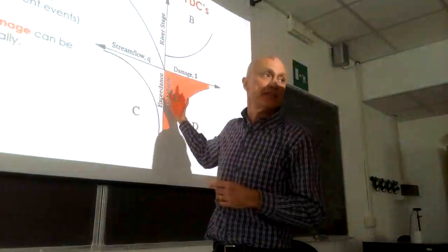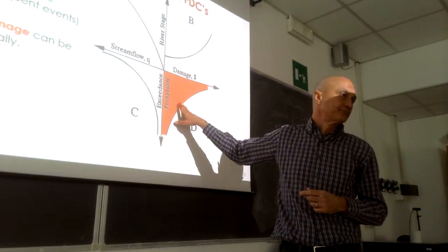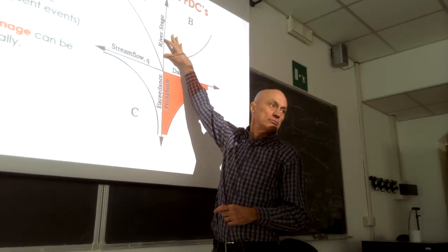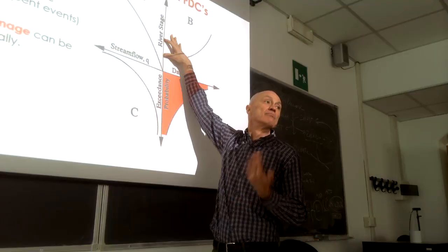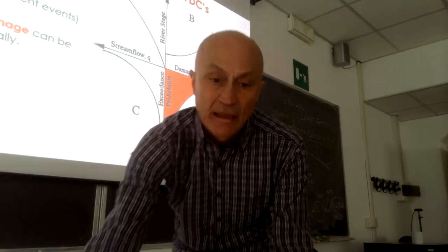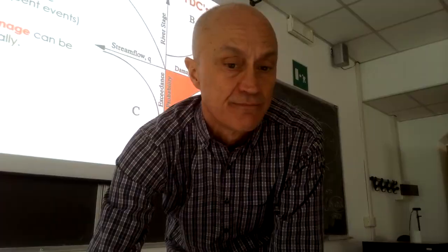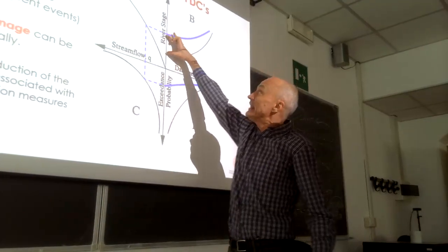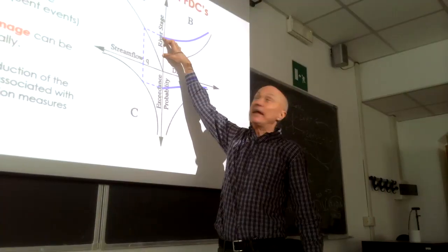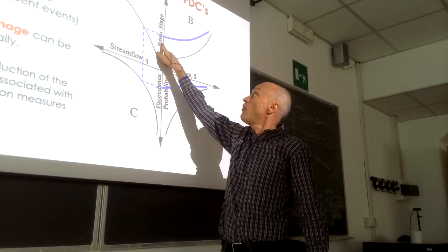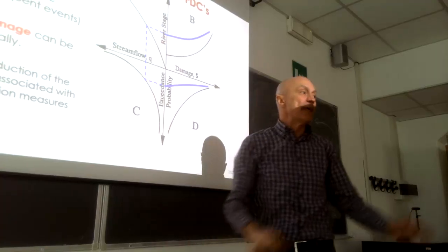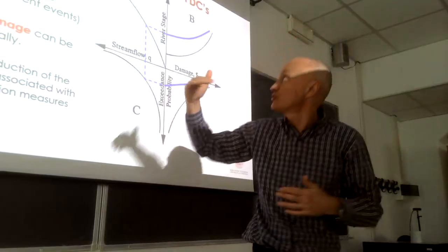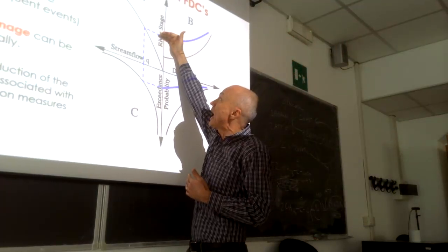So, if I build a levee this tall, it means that the river stage can go as high as this point and the damage will be zero. I will start seeing damages only for river stages above this point. Do you follow me? And then, of course, above this point, there will be an increasing relationship again between river stage and damage, to simplify a very complex problem.